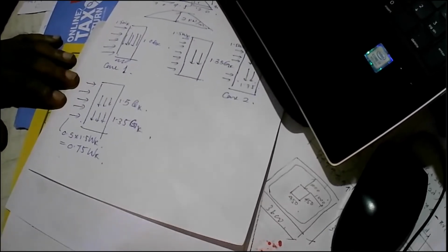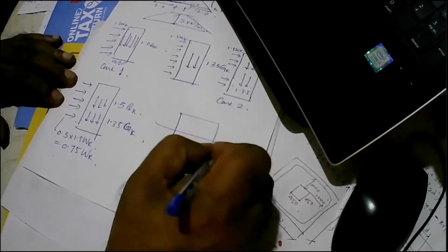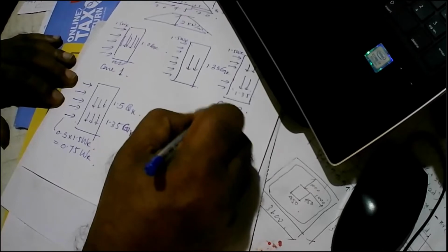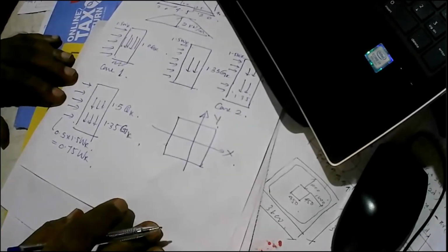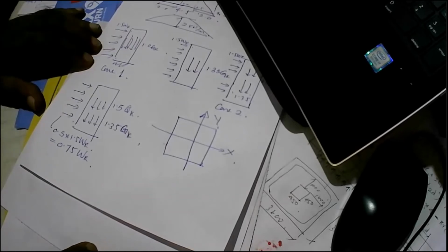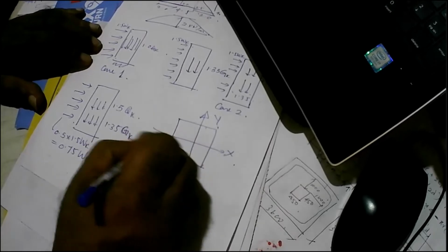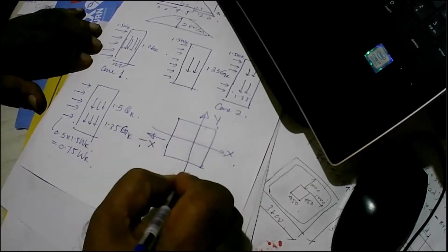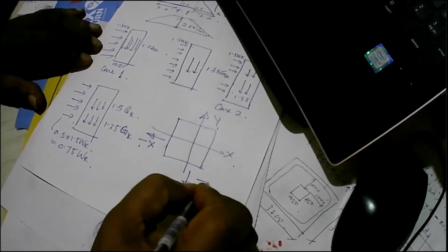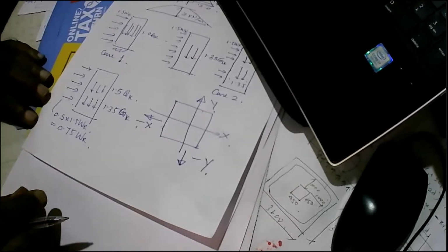So these are the loads that will act, and we have to consider the loads in X direction and in Y direction. So each of these cases with wind will get two cases, X direction and Y direction. And in addition to that, we can get minus X direction, minus Y direction. So you can get different cases.